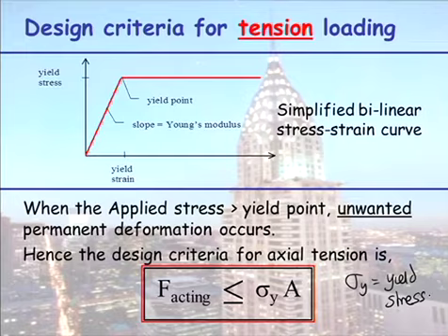In the design office, you will look the value up. So you'll be able to find that value. So extremely simple formula. And that's for members in tension. If I pull something apart in tension, in the end, how much load can I apply on here? The cross-sectional area times the yield stress of the material.